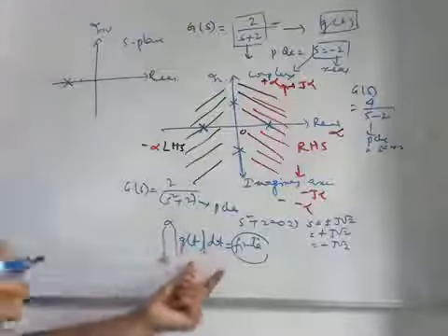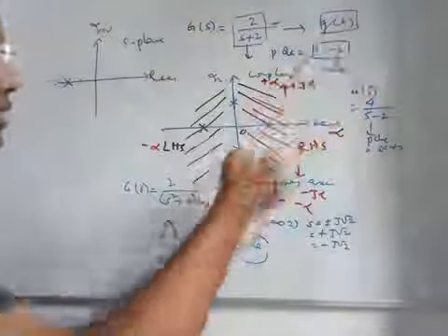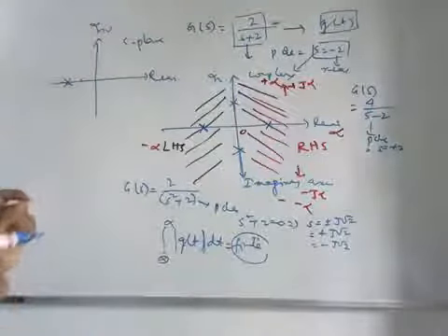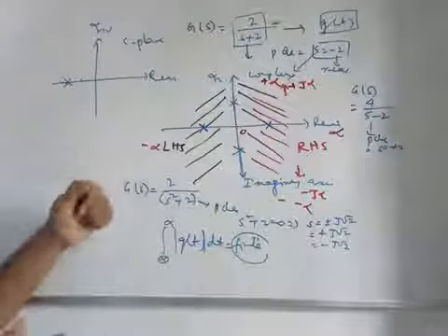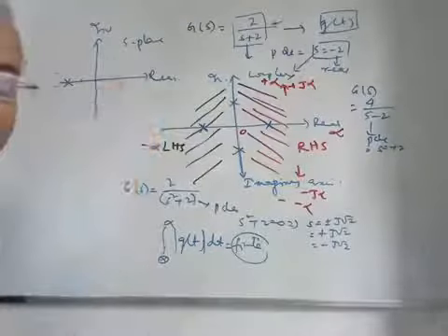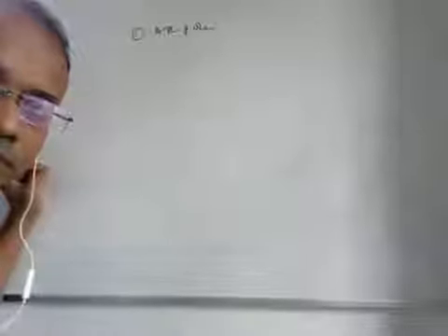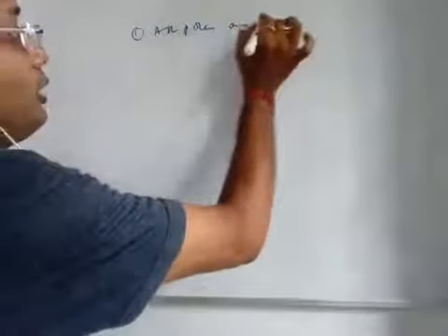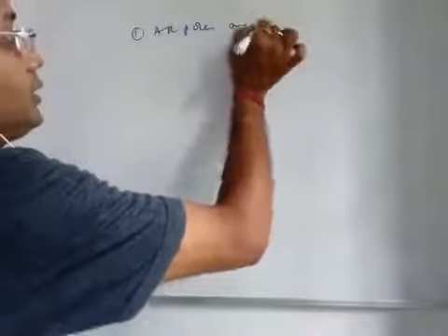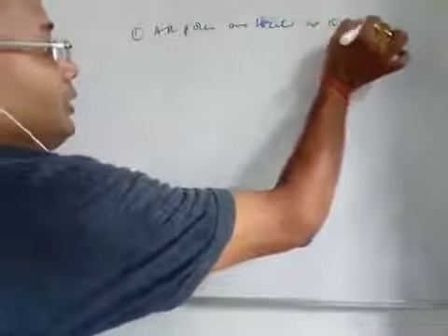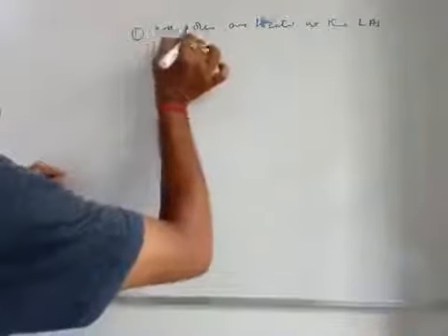So this is actually related to the pole locations, and in a broader sense I say there are three criteria which will be developed here, right? First of all, the criterion is like this: all the poles are located at the left hand side of the S plane.